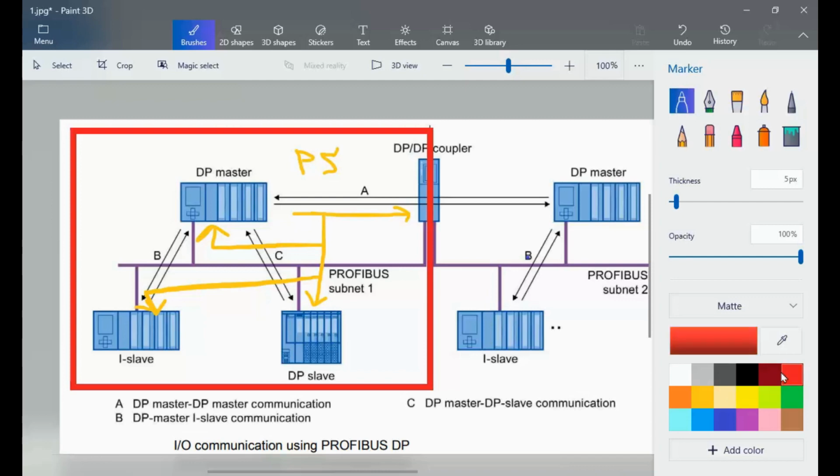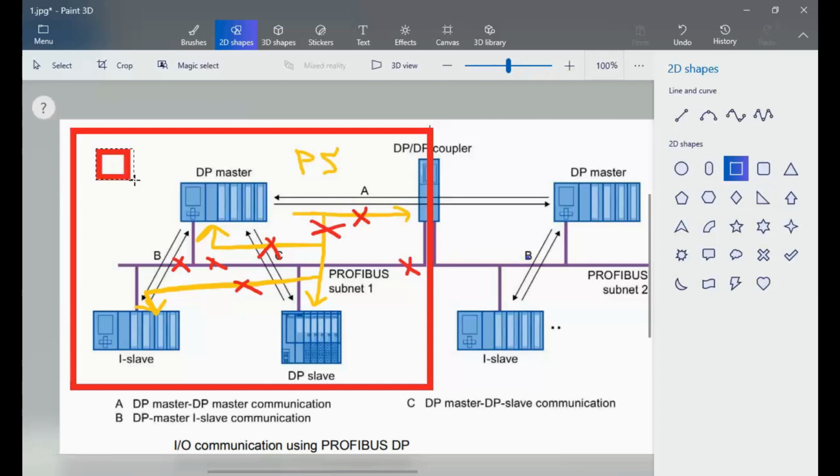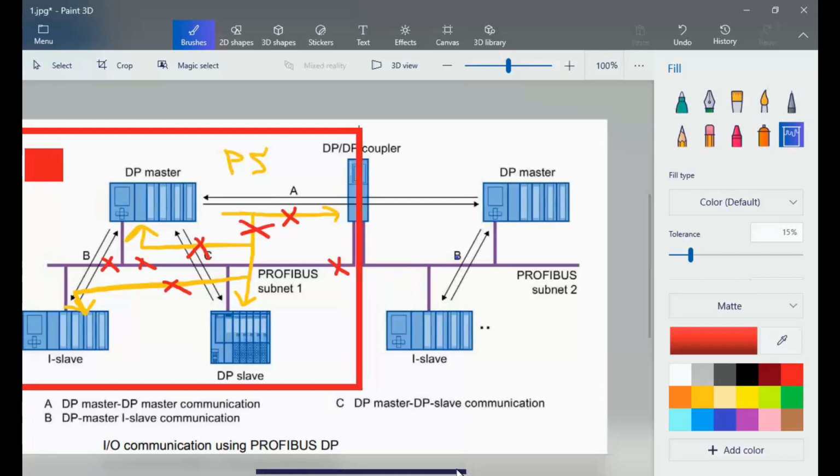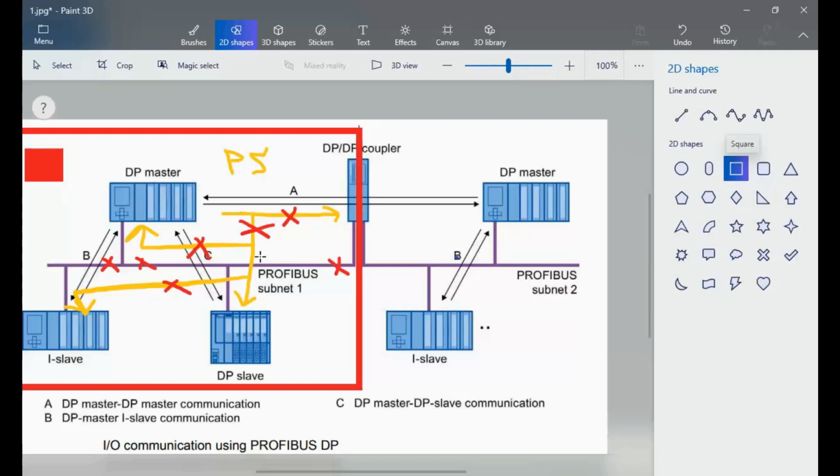If something goes wrong with the power supply here, or with the cable, you will have a PROFIBUS error here, while the other network is trouble-free and can communicate without any error, because the power supply in this master DP subnet is independent of the adjacent system.